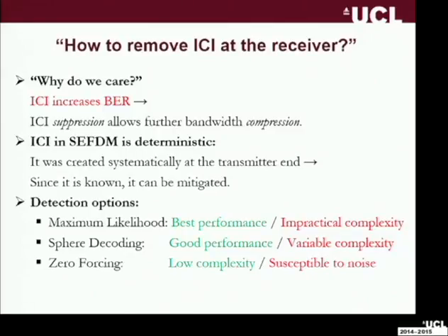Now, sphere decoding has its roots in another theory called lattice decoding, which can be traced back to the early 1990s. What that does is it constrains the solution of the maximum likelihood. So instead of searching absolutely every single combination, it takes a first estimate, which in this case could be zero forcing or some other simple detection scheme.